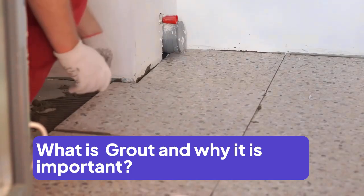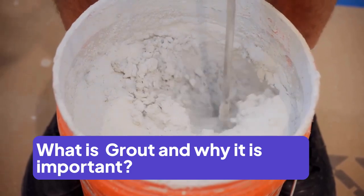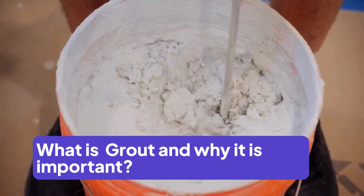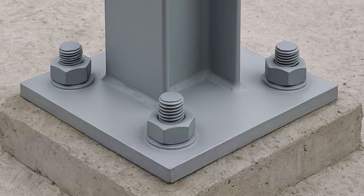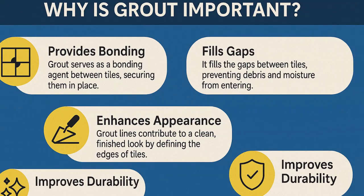Now if this joint is not treated properly, the water will penetrate inside the base and destroy it. So we need to treat this joint to make it watertight. You can fill it with grout material. Sometimes it is used under the base plate: on the concrete base you erect a structure, and between the base plate and the concrete surface there is a gap. If we do not fill this, there will be a problem of load transfer as well as structural durability. So in that case also we need to fill the voids, and that is called grout.